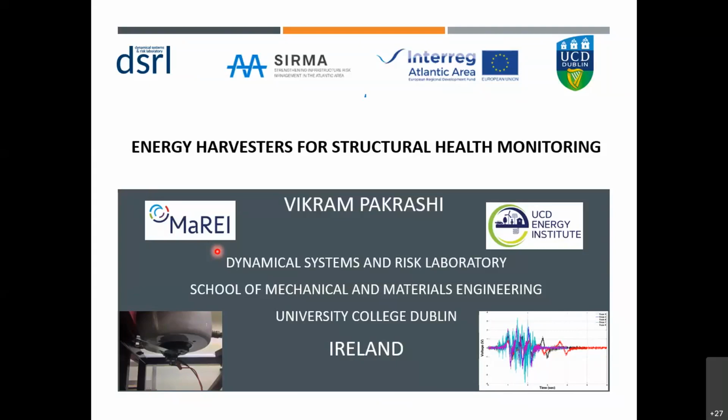With energy harvesting, the way I see it is, then it passes through a second set of dynamics. Let's say we have a cantilever type harvester at the end, and then the output acceleration goes into this cantilever, which is another set of filter, and it creates, for example, strain at a certain point where the harvesting material is situated.